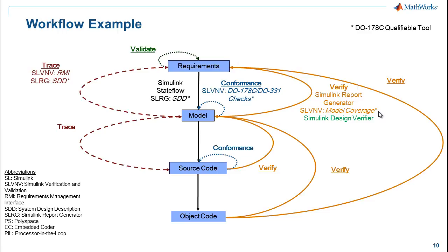And again, there's two ways to go after that problem. We could try to come up with all of those possible scenarios, which we don't have time to do. The other is using a tool like Simulink Design Verifier. We could attempt to do what we would call property proving, where you could give that requirement some kind of mathematical meaning, and then in some cases we can do that closed form proof to show that the model will always exhibit that behavior.